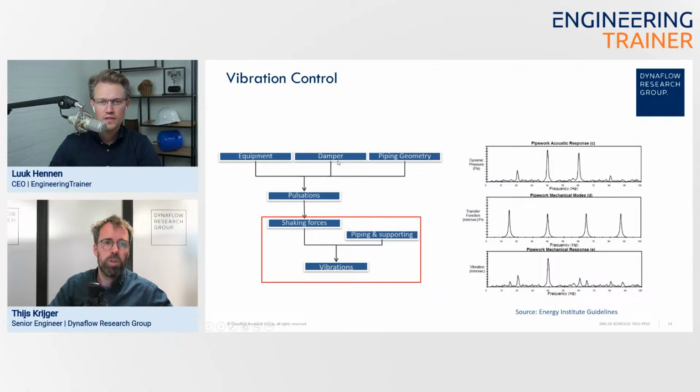There's also possibilities if you have some acoustic resonances. You can use orifice plates to eliminate those, because the orifice plate will kind of force a reflection point where you place the orifice. Yeah, you kind of cut a wave in half or something. That's how I think about it, I guess. Yeah, I think that's a good image indeed.